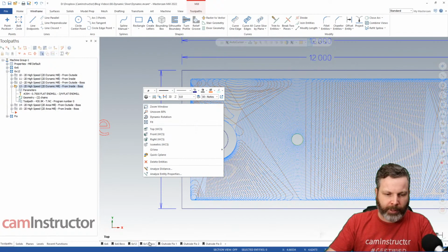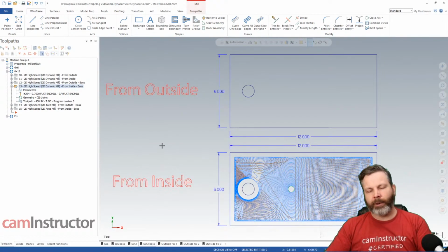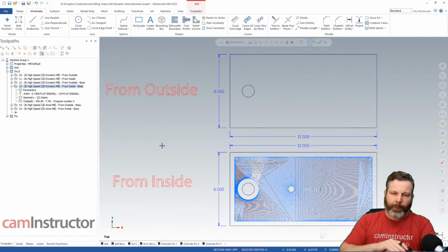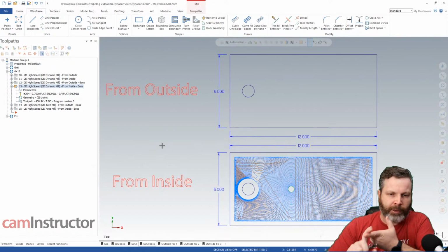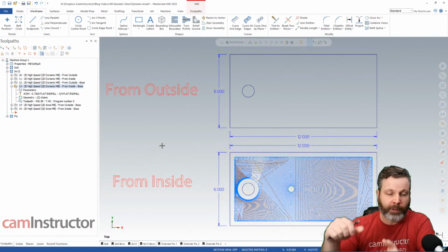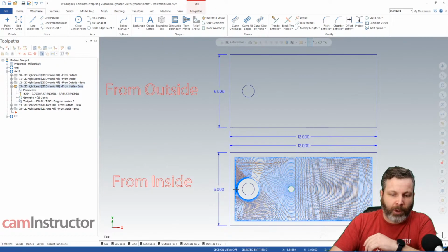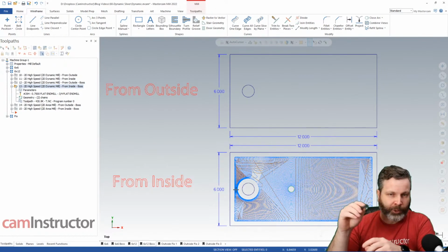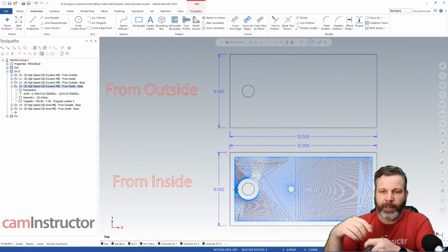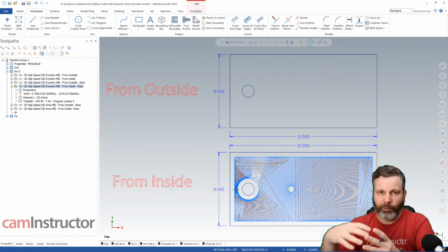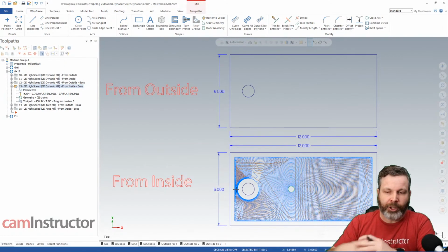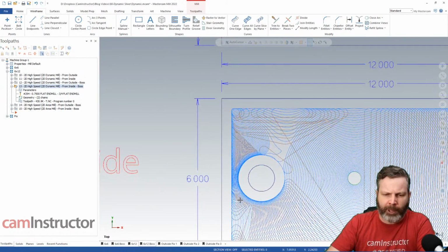Okay, so let's get back into this. So there's our 2 scenarios that can come up. Number 1, the sliver inside of a from outside toolpath, and number 2, small arcs allowing a tool to fit into a tight section that gets our feed rates higher than, or our chip load higher than we expected. I guess we could make the argument in this section as well.